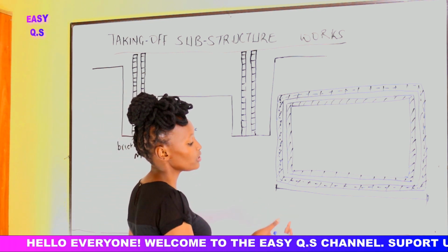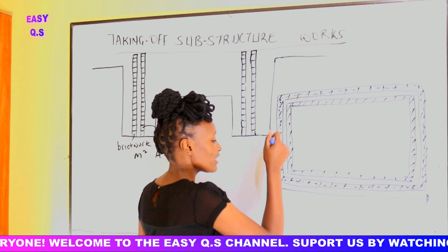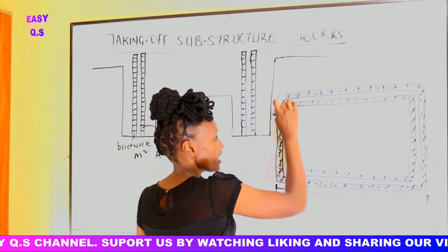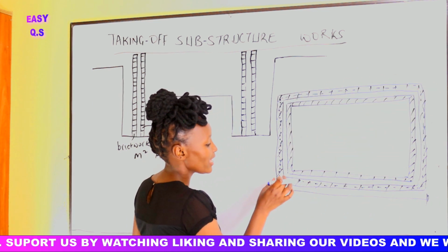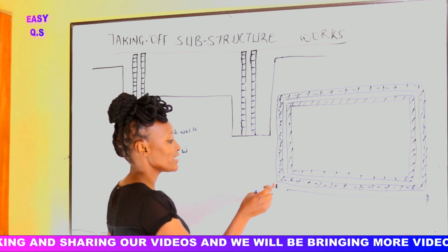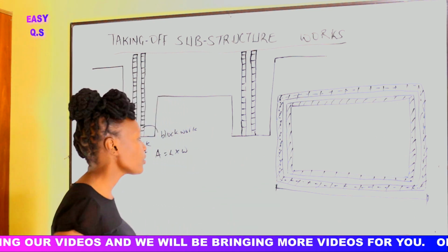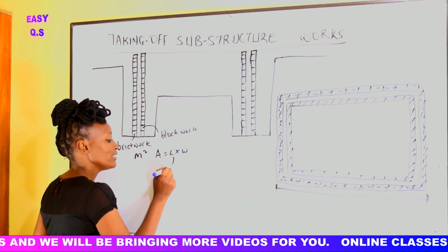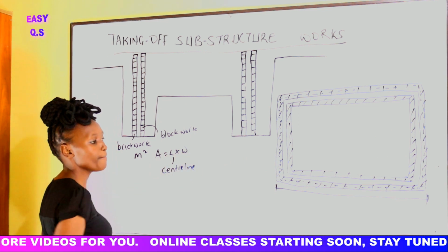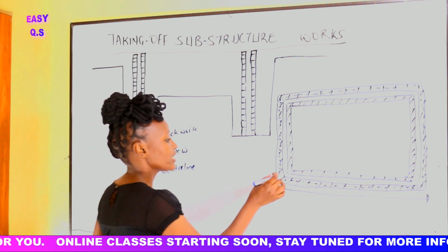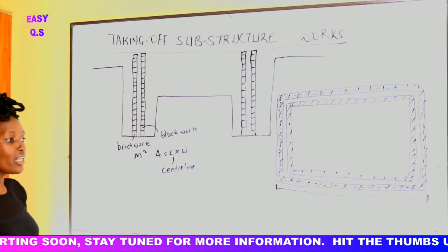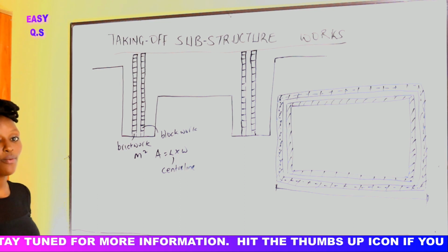So in simple terms, we shall take the external perimeter of the building, we deduct number of corners times the thickness of the brickwork, so you'll get the center line of the brickwork. Once we take the center line, we multiply by the width of the brickwork. Width is the thickness of this brickwork. So that one, we shall have found the area of the brickwork.